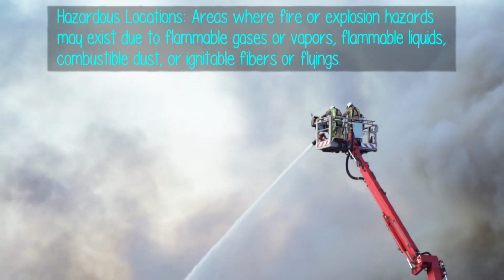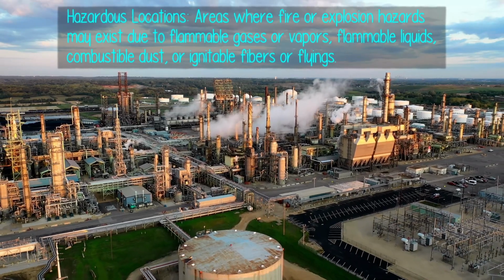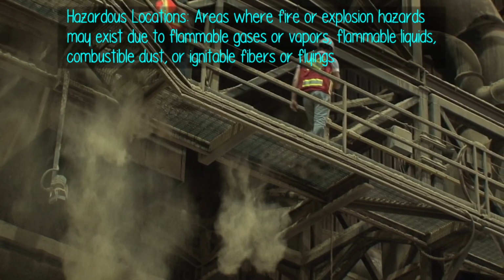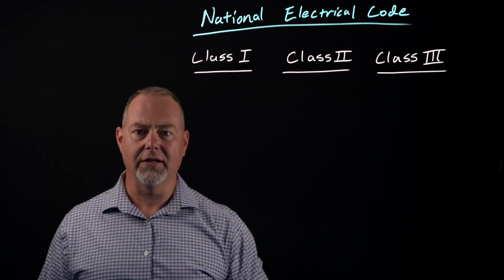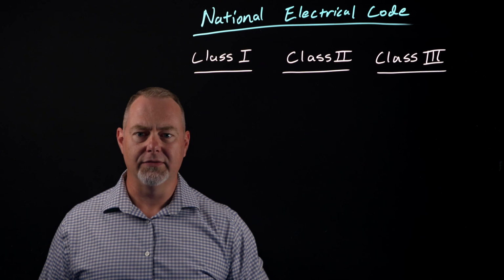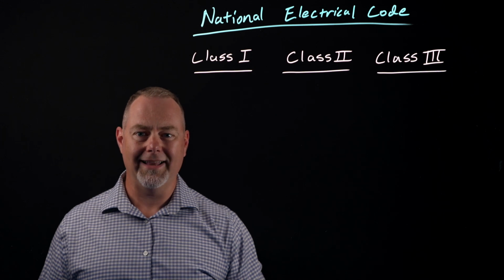It defines hazardous locations as areas where fire or explosion hazards may exist due to flammable gases or vapors, flammable liquids, combustible dust, or ignitable fibers or flyings. And the reason this falls under the NEC is that electrical equipment can easily become a source of ignition in these volatile areas. These hazardous locations are then divided up into three groups known as classes.